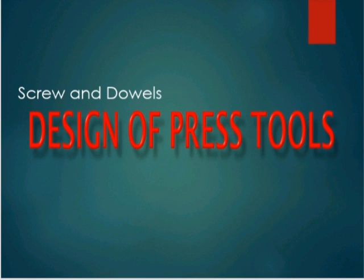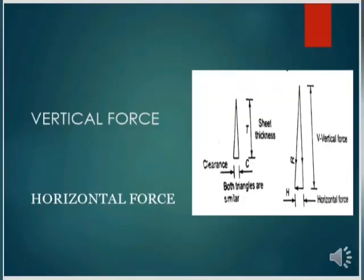Hello everyone. Today I am going to explain how to calculate the number of screws and dowels required for a press tool. Before starting the calculation, we must know there are two types of force developed during shearing operation: vertical force and horizontal force. Here, see in the figure, force developed in the shearing operation can be represented by a triangle.